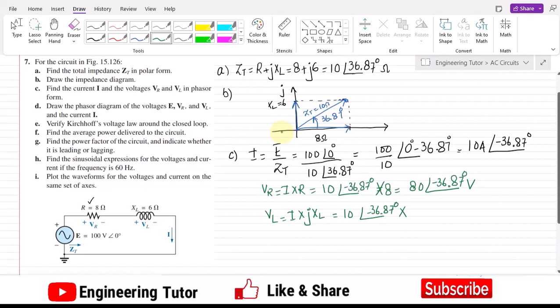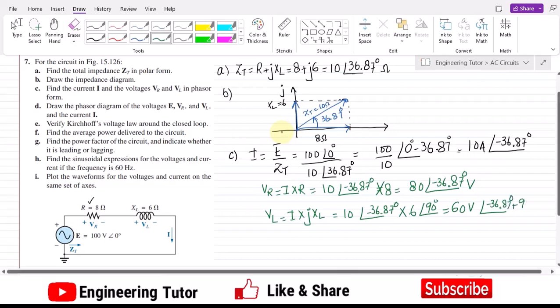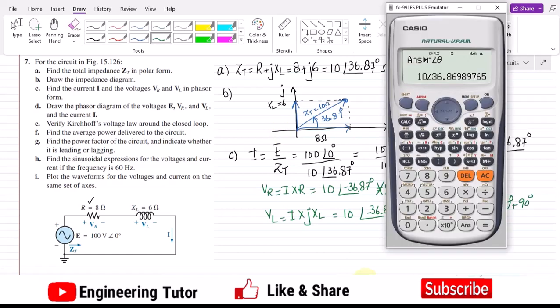The value of XL is 6, but j is included with it, and I have told you that whenever you have any quantity with j, or an imaginary quantity, we write the magnitude, and the angle with it is 90 degrees. So now the values will be 6 multiplied by 10, which is 60 volts, and the angle it has is minus 36.87 degrees plus 90 degrees. So how much would it be?